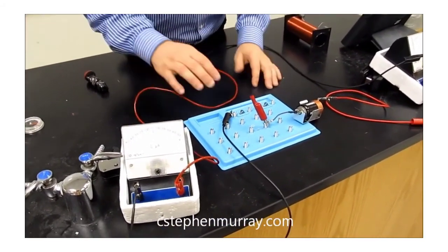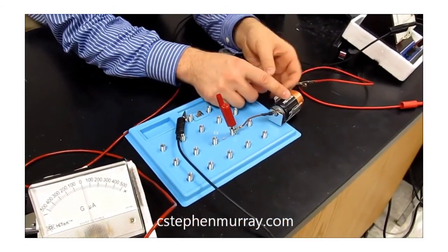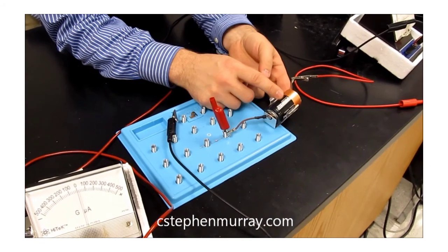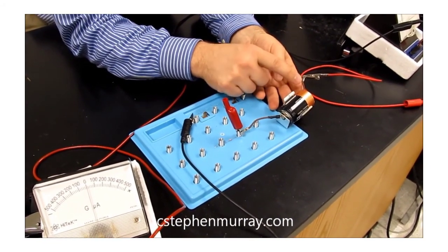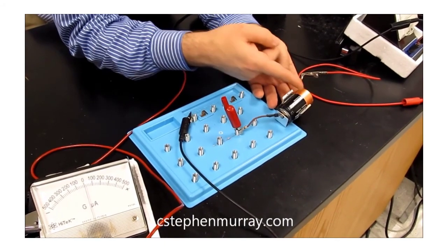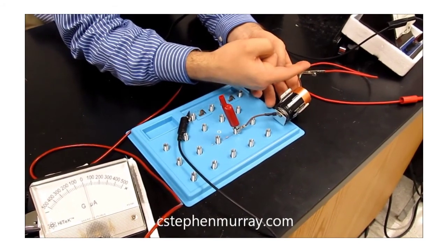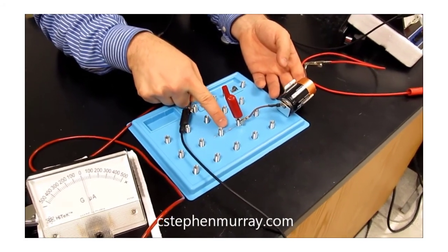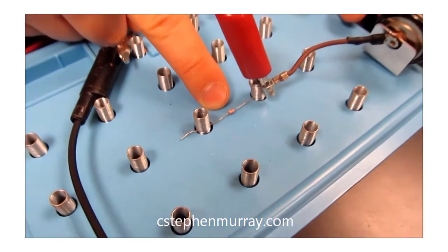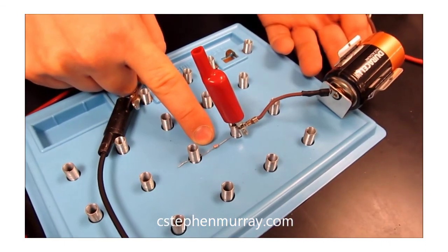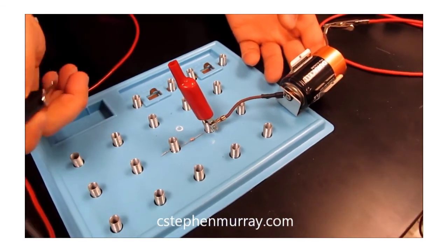So let's find out how the galvanometers actually work. I have here a 1.5 volt battery, just a basic Duracell. Why did I pick a Duracell versus anything else? Because it has that copper top and it's very easy to see. That's the positive. I guess I could use a marker there to show that. So this shows the direction of positive current flow. That right there is a 6.6 kilo ohm resistor. It's 6,600 ohms. Why? Because I have to get the current low enough so that it will read on the galvanometer and not hurt the galvanometer.